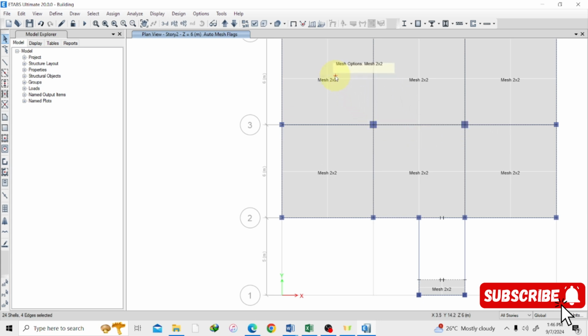Looking at our slab here, you can see these lines through them. These are the mesh in the slab. If you see that maybe your mesh is too big and you want to reduce it, you can go to previous select. So these are the mesh, these lines cutting through, but you should also make sure that these lines are continuous throughout. This line can't be here and we have another line disconnected over there. It has to be continuous throughout.